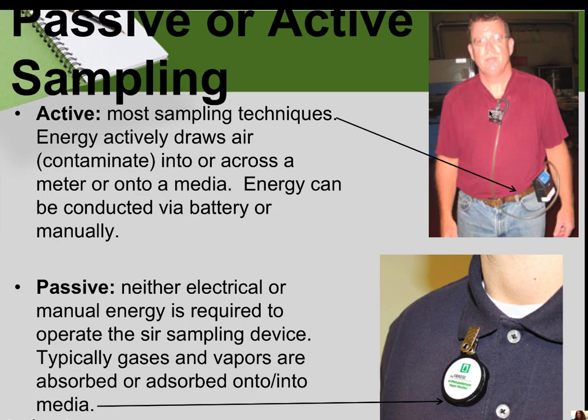So here's our sampling media. The air is being pulled across the media into the pump and is then, of course, filtered and discharged. And the sampling contaminant should be deposited on our media. This should be as close to the breathing zone as it could be. Up on the shoulder would be a little better.